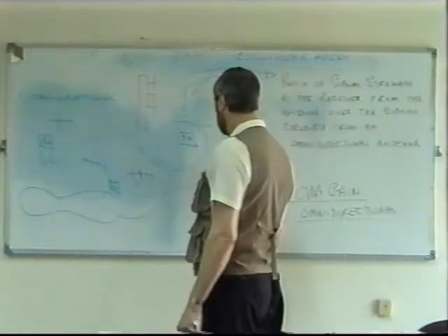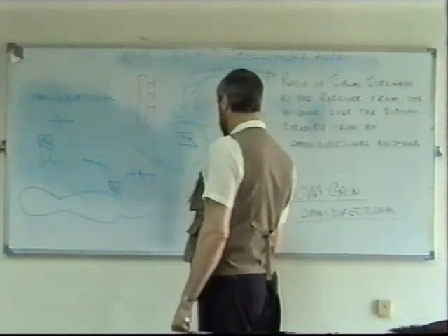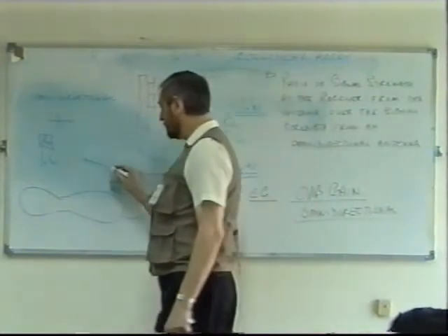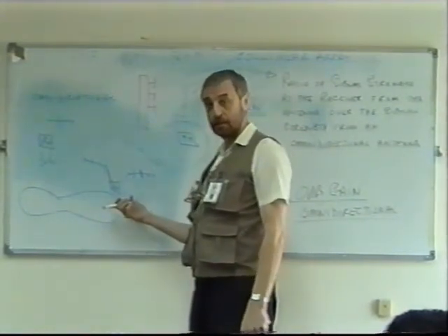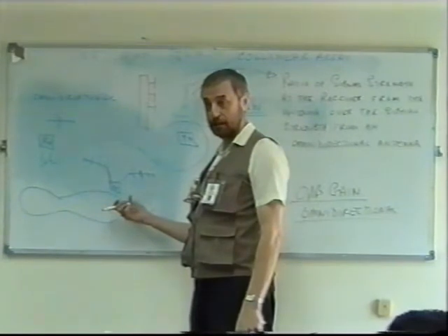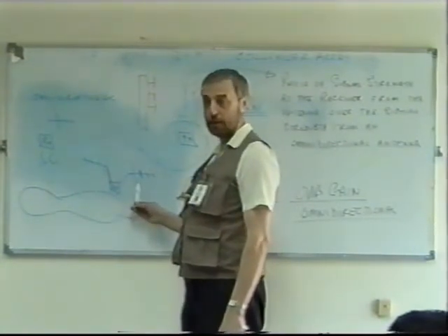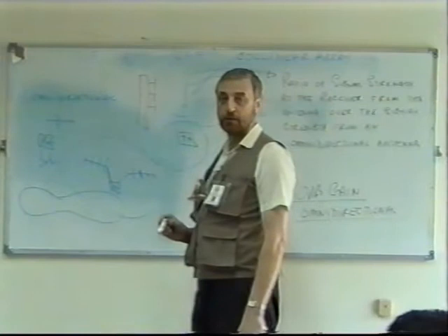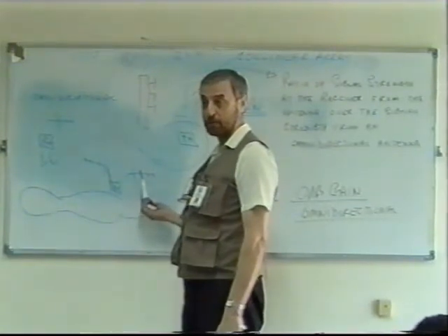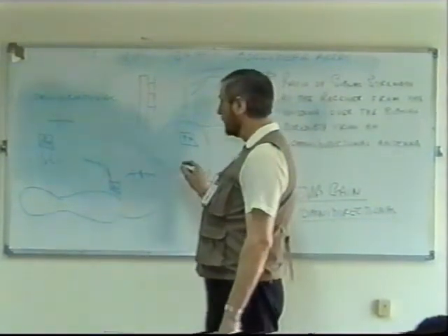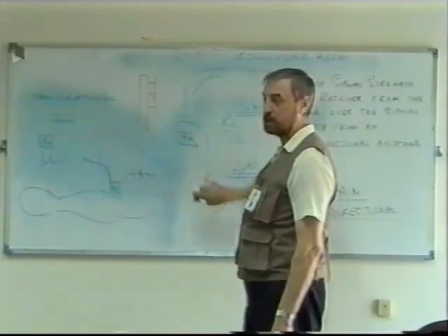Here I have a receiver. I have a transmitter connected to one antenna. I'm going to get a certain signal strength, say 1 microwatt. Doesn't matter what it is. Now, I then connect another antenna, assume I connect it properly, matched and everything, to the same transmitter. Same power from the transmitter. Now, it should be clear that that power has now got to be divided between two antennas. So you would expect the power from this antenna to be less by about a half, because half the power goes here, half the power goes there. That's a 3 dB change. So, if we look at these two antennas together, the radiation pattern in this direction has been reduced by 3 dBs.